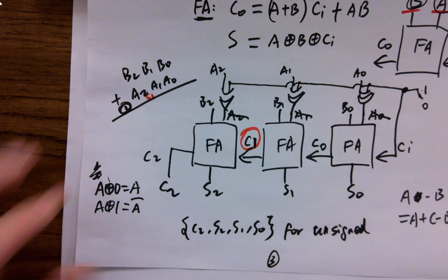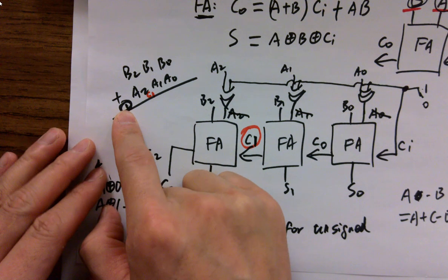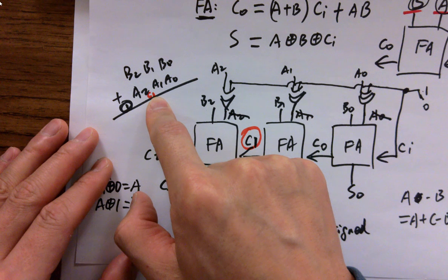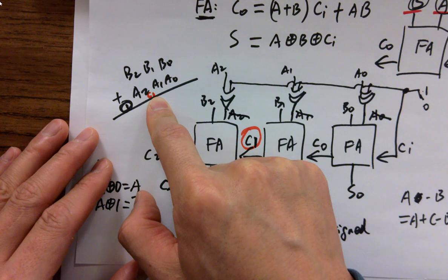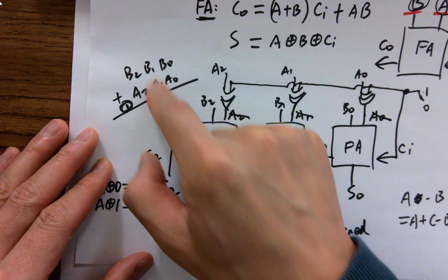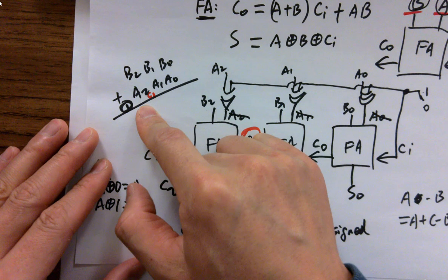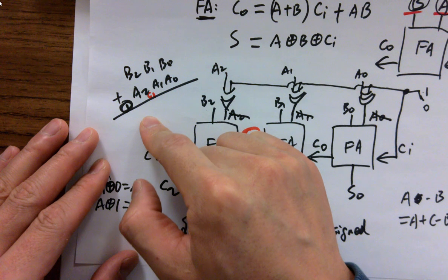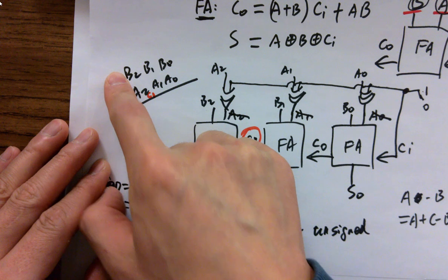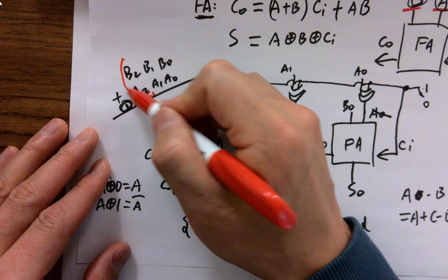So eventually the bits that determine if you are adopting C2 or not are actually A2, B2, and C1. Agree with that? You don't have to worry about this one because C1 is right at the final result of this addition here. And you have to look at this number because you want to determine if its final result is PPN or NNP. You have to know A2 and B2, so they have to be both zeros or ones in order to make overflow happen, right? So eventually you are only looking at these 3 bits.